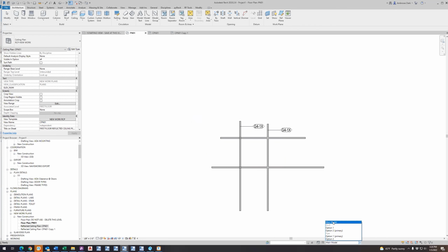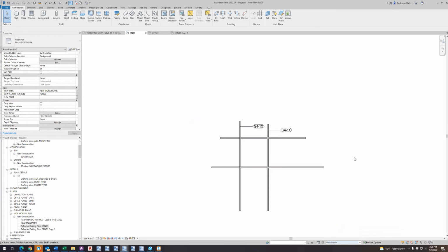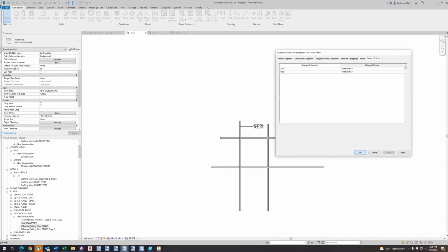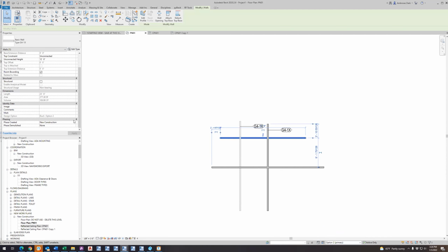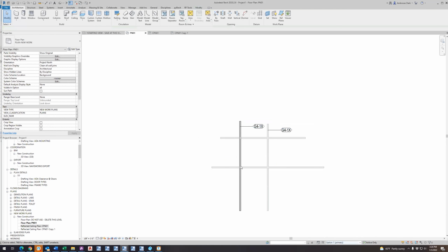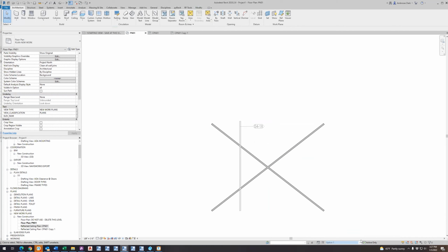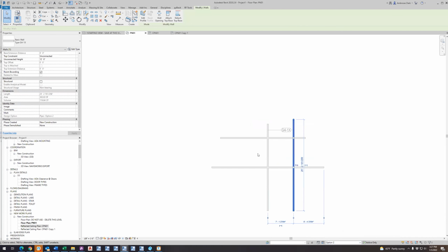So in this case, our main model is showing, which did I change that? Nope, set to automatic. So automatic is going to show option 2 of duct and option 1 of pipe, which is what we're seeing here. You can't select any of these, but if we go to those primaries, you can see in properties, it's duct option 2. All threes are duct option 2, and this is pipe option 1. And if I switch to a non-primary, you'll see them. You'll see what's in the main model. You just can't touch it.